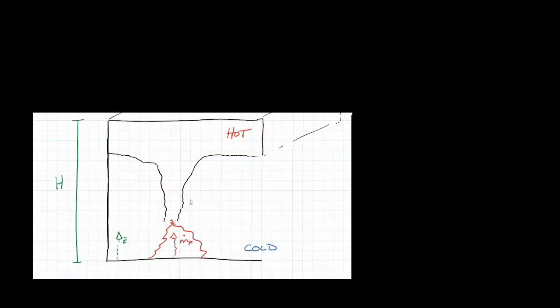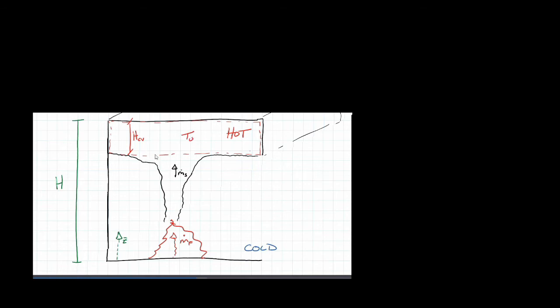So this is just a side view of a compartment, just to demonstrate the principles behind flashover. What you have is your smoke mass going up due to the forces of buoyancy. It's filling up this hot layer area at the top with this sooty, hot smoke that reflects radiative energy back. If you recall, your thermal radiation is proportional to the 4th power of the temperature in Kelvin. So significant increases in temperature create huge energy changes as far as radiation goes.